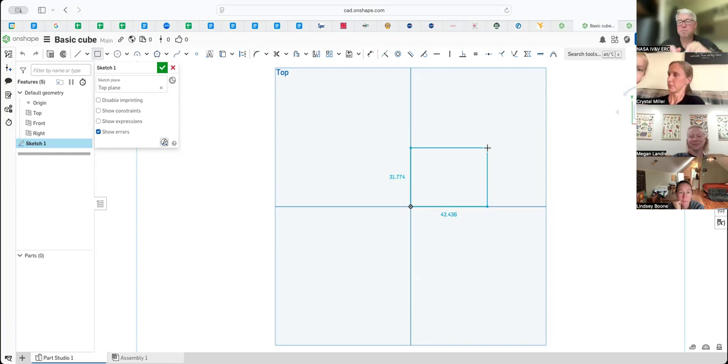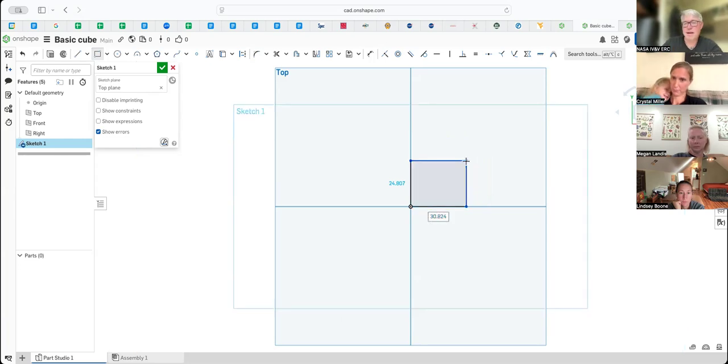So I'm going to make a 1-inch cube. When I'm dragging this, I could try to really look at those little numbers, but I don't have to. Once I click once with my mouse, it highlights, and you can see that box in the bottom is now white. I can type in what I want, 25.4, and I can press return, and then it highlights the other box, which I can type 25.4, return, and I've now made a square as a 1-inch square. These little dimensions right here show you the size of your object.